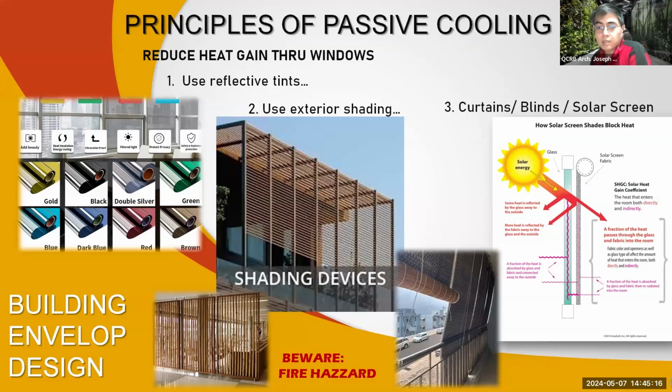heat or the light, the same reflection happens against the interior side of the glass. So parang may babounce off uli mo from the glass before hindi lahat ng mare-reflect na curtain is lalabas. So meron pa rin na papasok na heat. So ang pinaka-effective way talaga is using exterior shading first, and then ideally pag hindi mo kaya mag-exterior shading, like if you're in a building where you cannot put shadings outside, you tint your windows. And then afterwards, the last resort would be the curtains.